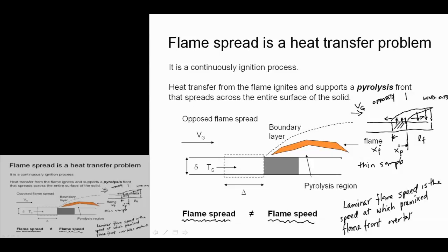Well, now, this is in some sense the limiting velocity that you're going to have in a flame spread problem. Because if, for example, there's a huge heater that's heating stuff even further than where the flame was heating, you can imagine that you can bring up the surface temperature of this condensed phase, this solid material, to the ignition temperature, at which point it's liberating pyrolysis gases like crazy.